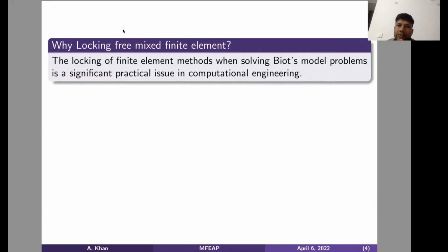Why a locking-free mixed finite element method? The locking of the finite element method, when solving either an elasticity problem or the Biot model, is a very significant issue in computational engineering. If we solve a nearly incompressible case, it is difficult with a conforming finite element method.